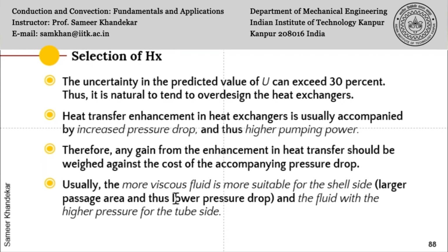This is logical. And also, if out of the two fluids one of the fluids is more viscous, since we know that enhanced viscosity will give you enhanced pressure drop, we would like to put such a fluid into the heat exchanger where the area available is more, which is usually the shell side.